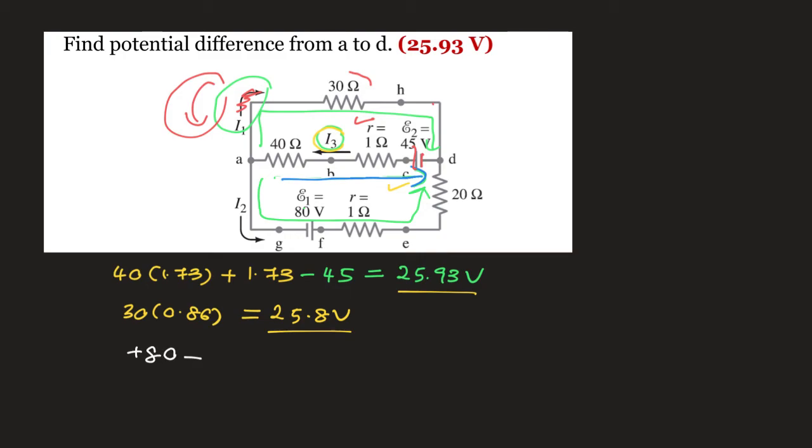The voltage here is going to be negative because my assumption loop and my current inside the circuit are in the same direction. So you are going to get negative 2.59 multiplied by 1 ohm, and then the 20 ohms also negative, which is negative 20 multiplied by 2.59.